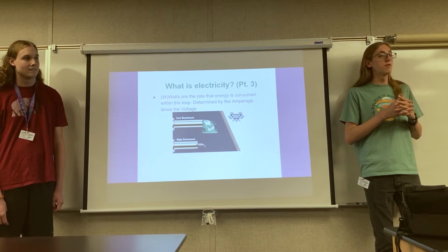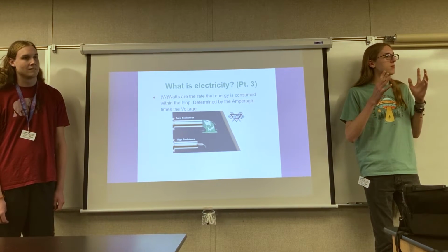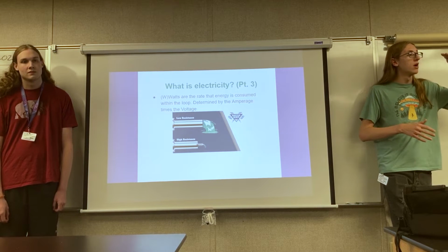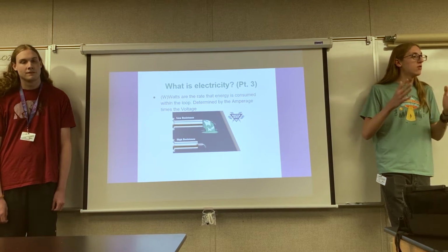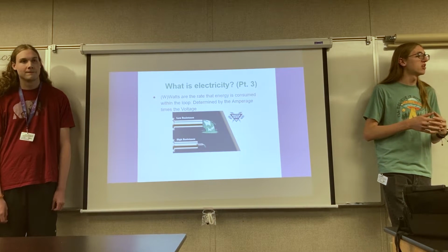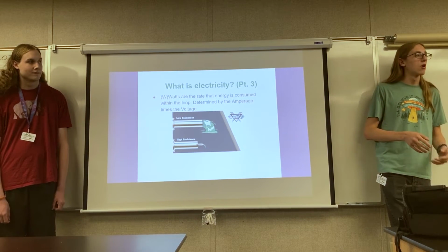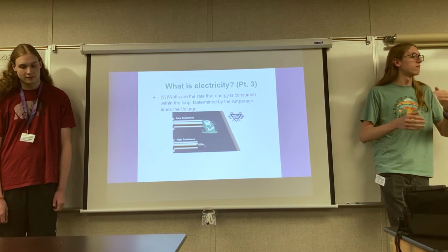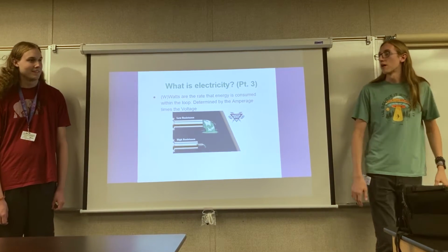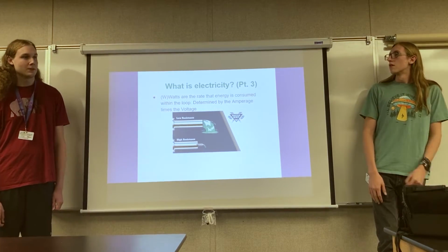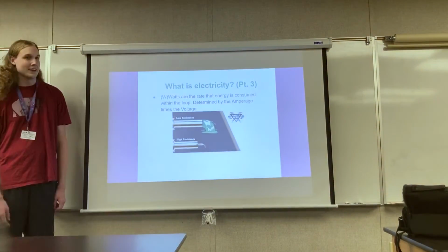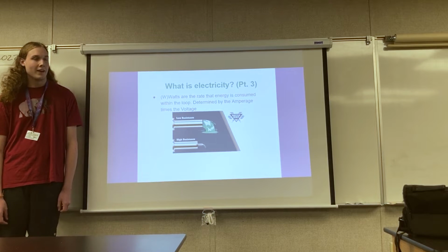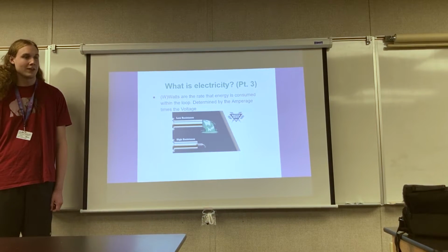Whereas our 5 volt ones, and there are actually some of the 12 volt ones that are regulated, but for the most part we're dealing with our 5 volts, and that's our brain. It runs on a power regulator, which makes sure that the power isn't fluctuating, because the robot will draw a lot of power when in motion. For example, the network switch or the router, we don't want that to randomly lose power in the middle of a match because the motors are drawing power. So that's why we have the voltage regulator module. You can get pretty large jumps when drawing from the motors, between 10 and 14 volts. But the motors aren't that picky, so they don't need to be as regulated, and they're more directly connected to the battery.